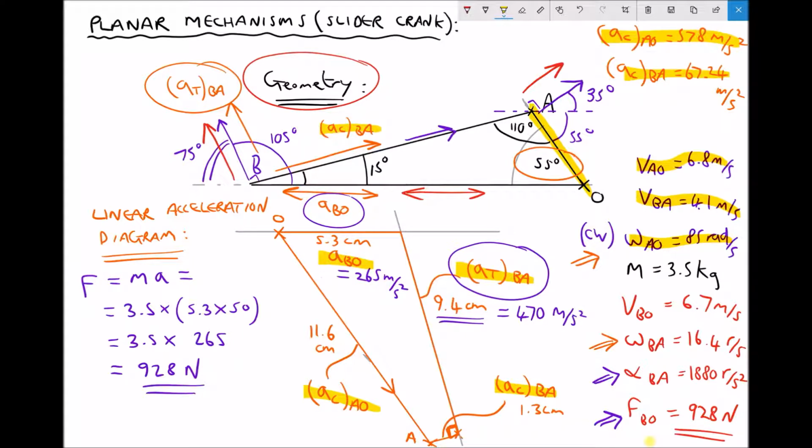So there's a number of different steps there, but the important thing to being successful with these scale drawings is drawing the diagrams as accurately as possible. You need to use a sharp pencil, you need to set up datum lines to make sure your angles are accurate, and you need to measure lengths and angles very accurately throughout the tasks.